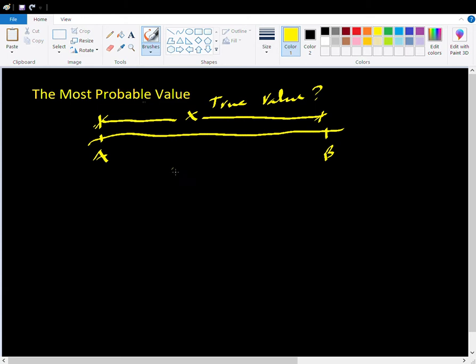To answer this question, we might go in haste, grab a measuring tape, and proceed to the field and measure the distance AB. So you place the 0 mark of the tape and then you unwind the tape. Say you were able to get the distance 45 meters. But is this measurement of 45 meters indeed the true value of the distance between A and B? Well, not quite.